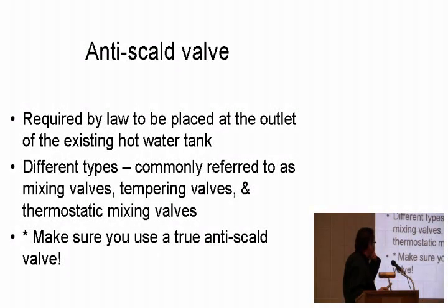I just want to touch a little bit on the anti-scald valve. Anytime a hot water heating system is changed now, you have to, by law, put an anti-scald valve on. And it's a very good idea anyway to have one, because there's a huge number of people still getting burnt by hot water overall. A true anti-scald valve will prevent that, and it goes on the outlet of your existing hot water tank.